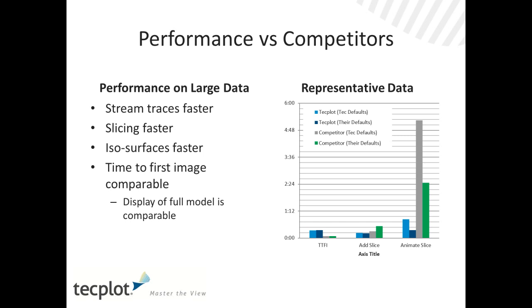that you can present and say, well, here's how it compares to test, for example, and that's why we have high confidence. Then we verified that this case actually verified the code gives the right answer, and then validated it against some tests, and that's really, at the end of the day, what we're trying to do here. It's not to show a picture of vortex shedding per se, although that can be helpful as well. So you can't focus just on the big data 3D visualization. In the end, there's this cascade of information down to these engineering plots, and that's where decisions are typically made. It's on the engineering plots.